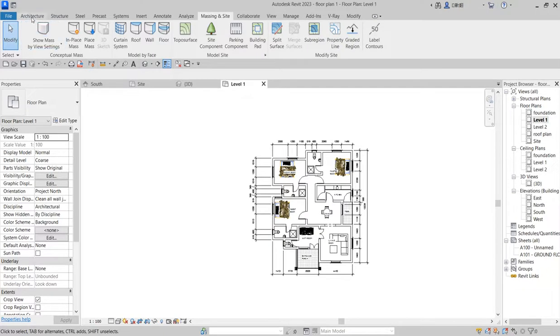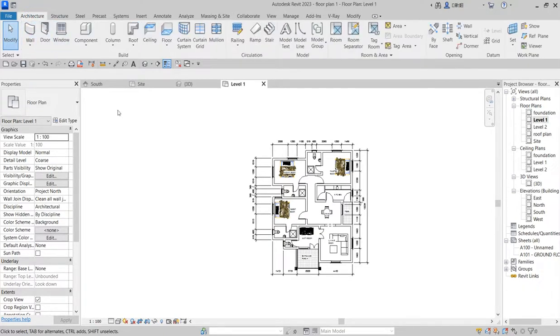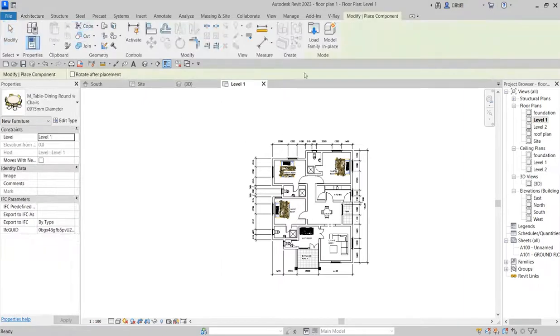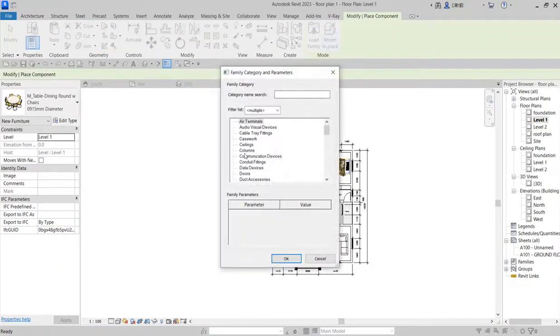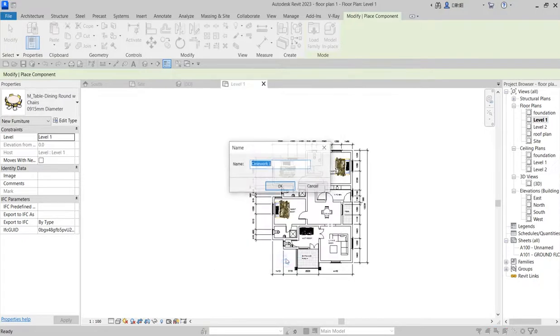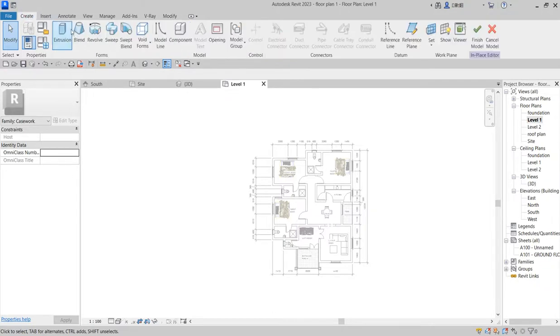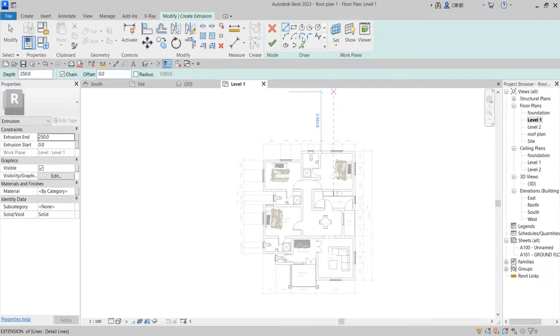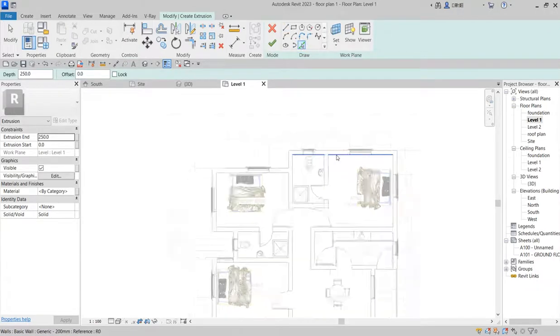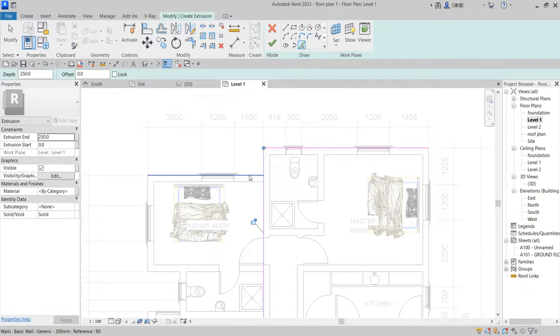So click on your architecture, then click on model components, and model components say model in place. What we want to do is to create, so model in place, write site work. Okay, say click OK. From here now, this one will guide you on how to place your boundary around the building. So create, we want to use extrusion instead. So use a pick line to pick all the lines.